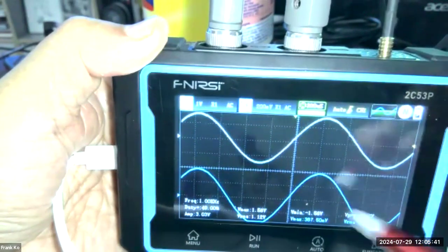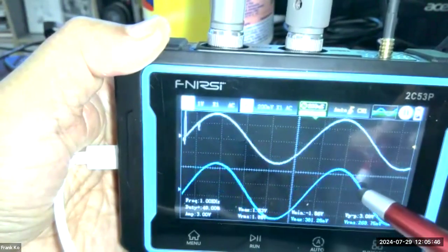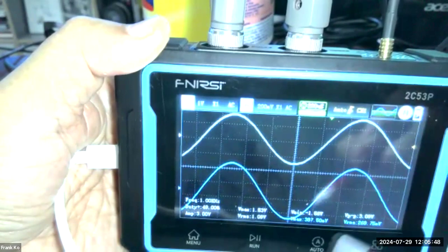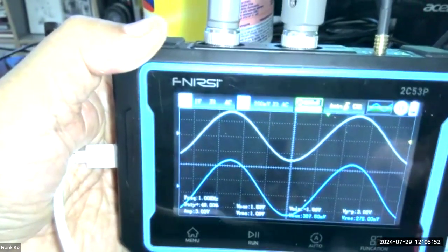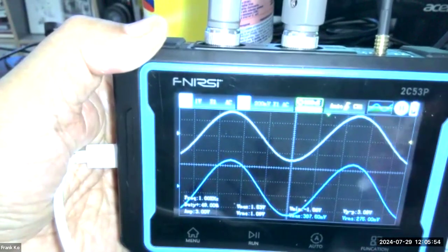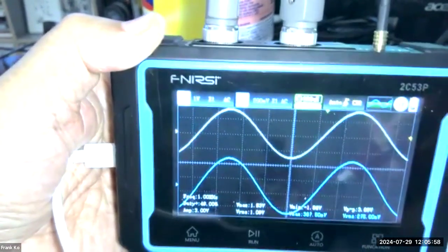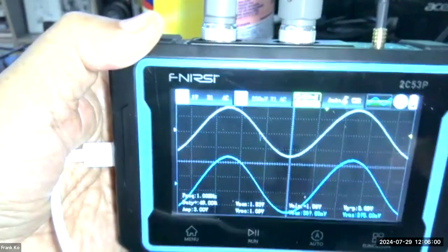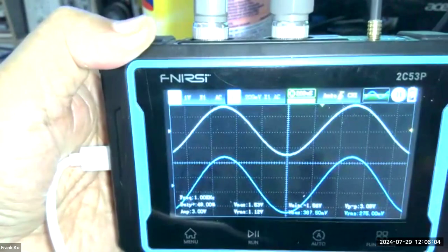Now the RMS, again, the waveform comes right down in front of that. So I can take my touch pen and move this over like so. And then now I can read the value a little more clearly. And it works out to be 275 millivolts RMS, which is not far away from our 261.85 millivolts RMS that you should have written down in your journals. So let's compare and see how these values compare with your journal.